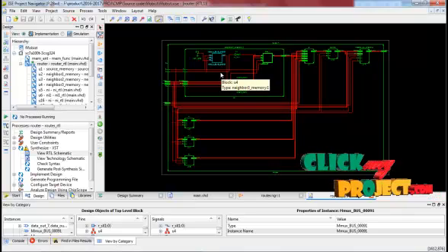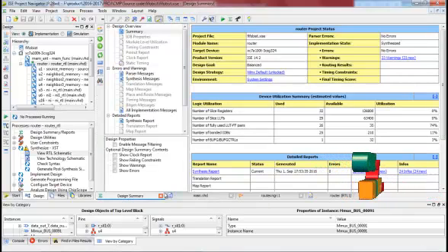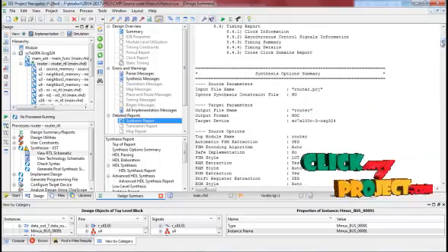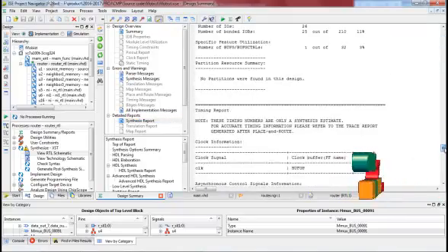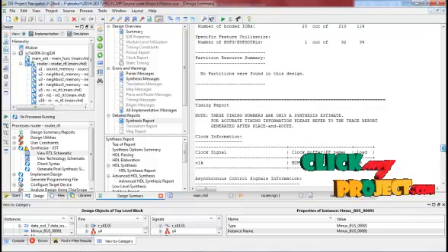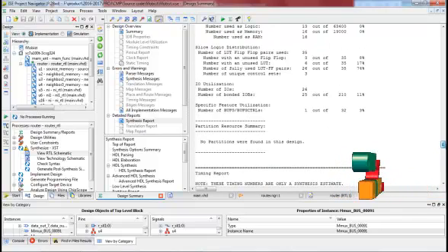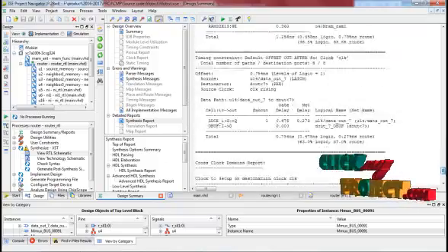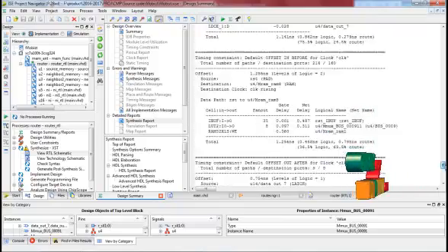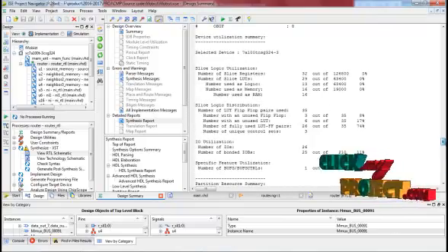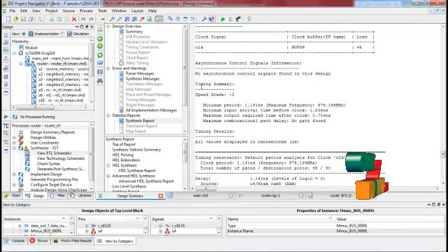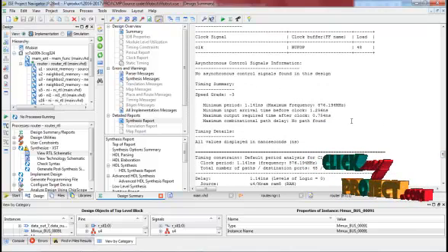For running our design summary, how many flip-flops and LUTs are used is displayed in this place. So this is our number of flip-flops. We have to use fewer flip-flops and LUTs than the existing system. We have to reduce all these things. Also we have to reduce the time delay, the minimum period and the clock arrival time.